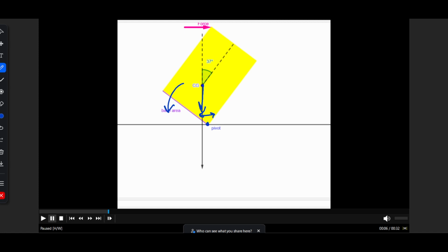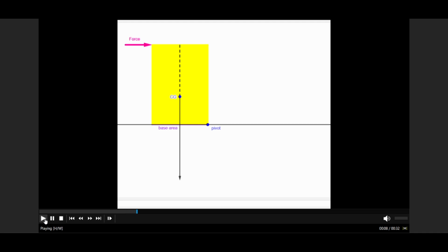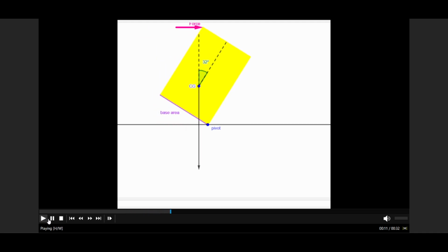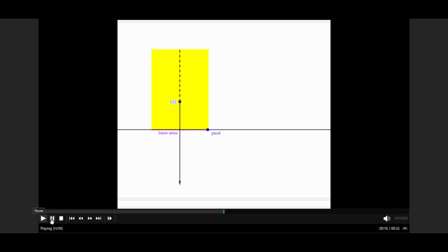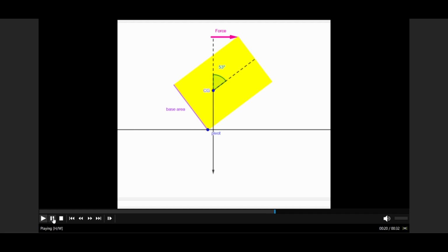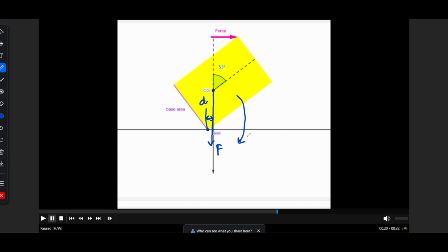And if we observe this, we can see that if it is allowed to fall down, the box comes back again. Again, we are trying a different angle at this point. Again, it falls back. So let's try a different angle this time, if we wanted to forcefully topple it over. Look at this point. At this particular instant, the weight vector is on this side of the pivot. From the pivot up to this point, this will be the distance and this will be the force. So this one is going to topple over clockwise if allowed to do so.